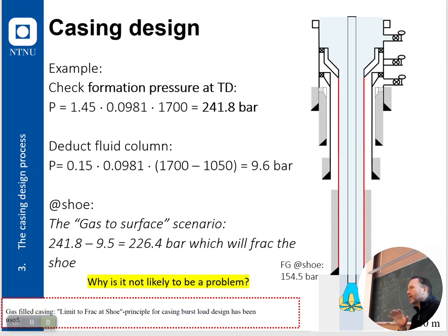Base oil would swallow the interface, if you see what I mean. If you try to push back what is in the well, you will always have a little bit of mixing in the front, right? And the base oil absorbs gas. So you pump some base oil and then you go over to mud. It could be oil based or it could be water based, doesn't matter. As soon as the mud itself hits the formation, you will see a huge spike in the pressure.